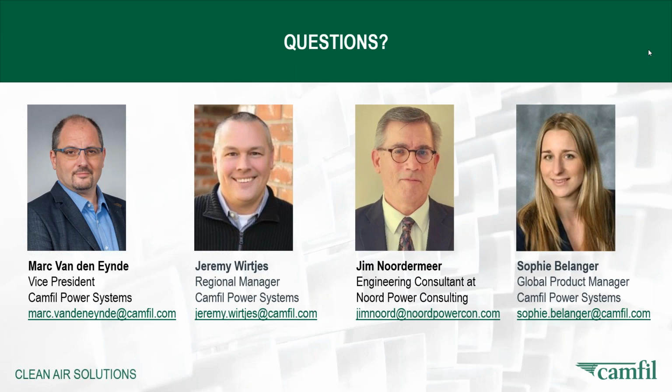So online washing is just like a delaying effect on the overall performance degradation that you will see on your gas turbine. Whereas air filtration is really the solution, because there you really avoid the engine getting sick overall. So you really keep it healthy, running efficiently at all times, and you don't even need to do all these washings, which is also at some point a cost and also a risk factor in the end.